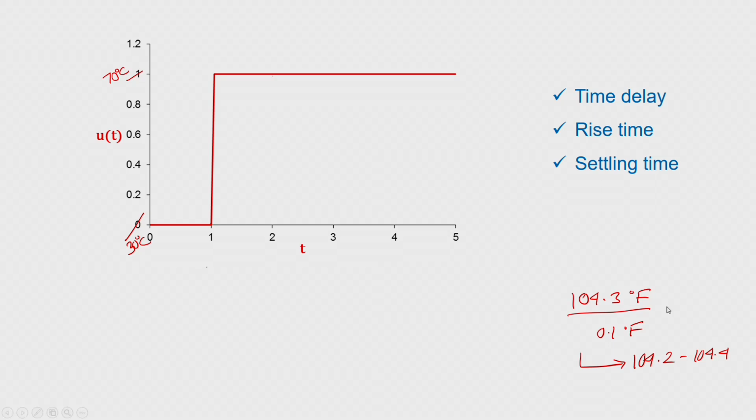This is a very simple device that we are talking about, a mass measuring platform or a thermometer, but there also you can see that the system is not able to respond instantaneously because of its own inertia, a pure natural phenomenon, and hence we have to allow some time to the system so that it can give us a proper output. How much time it will require depends upon the characteristics of the system. So, the rise time and settling time are important characteristics to judge the time response or time stability of a system.